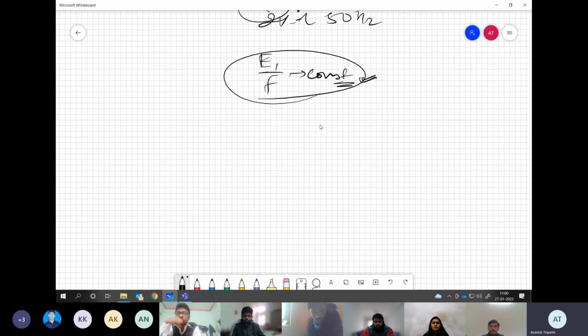Yes, sir, when we are increasing frequency, then we cannot increase the voltage more than the rated value. Yes. So certainly there are some restrictions, and not just on the higher side, on the lower side of the frequency also, we do have some restrictions. So this discussion we will complete tomorrow. And then we will slowly move towards our requirement, the need for a converter, and how to realize the power converter for this.